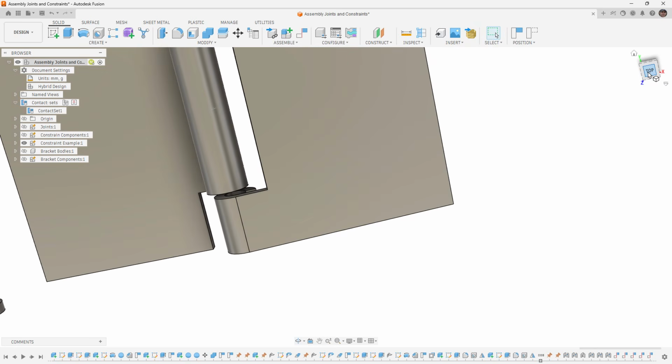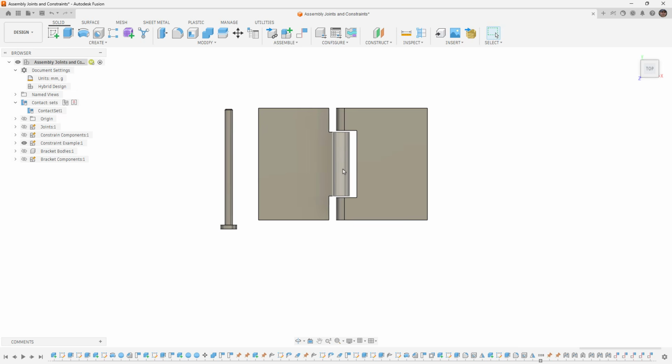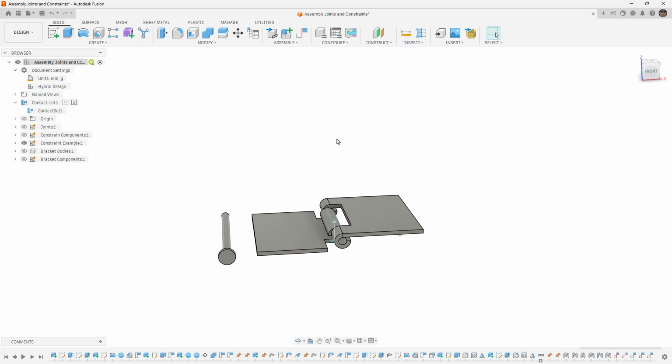And the between two faces, if we view this from the top, is because the brackets themselves don't share a face. So the faces wouldn't line up. They're sort of free to move back and forth. You oftentimes will have this when you're dealing with physical components. There's tolerances involved, there are gaps that are needed, especially with things like door hinges. These are going to have a gap between them. So we don't generally put two faces next to each other.